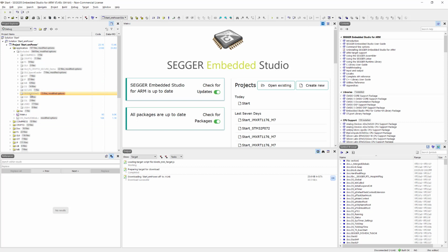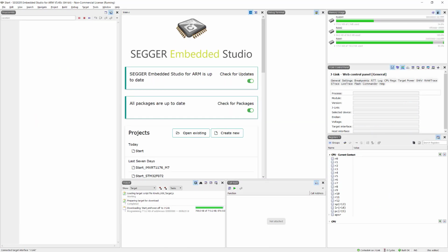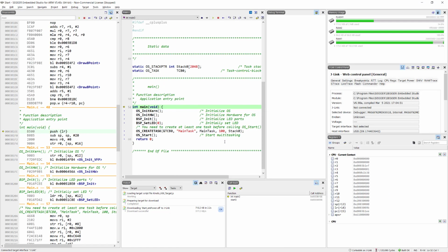In this case, the SEGGER demo is like a collection of various demos that we have for various peripherals and various parts of middleware. So I can just include that in the build and rebuild the application for this different demo. And then I have to obviously start a new debug session, and my J-Link is programming that, but it's so fast I can't even show you that. So again, we're sitting at main, and let's run this.